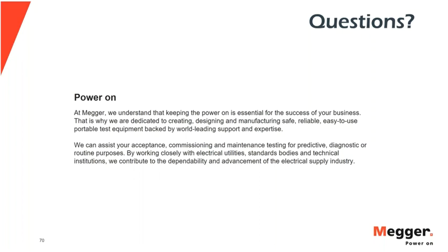And that way, if I determine that, gosh, the power factor is in fact still not 0.3%, it's 0.5%, then I can say, oh gosh, that's a pretty significant change from previous. So there's definitely some more testing in order here to get to the bottom of why that change has happened. So the short answer is that it is for the transformer under test.